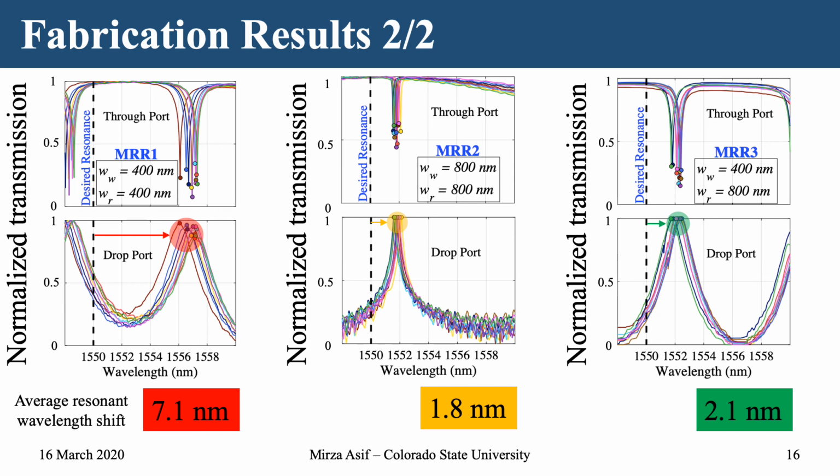It's not as good as seen in microring resonator 2, but it's not as bad as seen in microring resonator 1. So this gives us an amazing opportunity, and it proves our point, which says having your ring waveguide width about twice the input waveguide width would give you better tolerance, better coupling, and acceptable Q factor to be able to read signals at the output port.